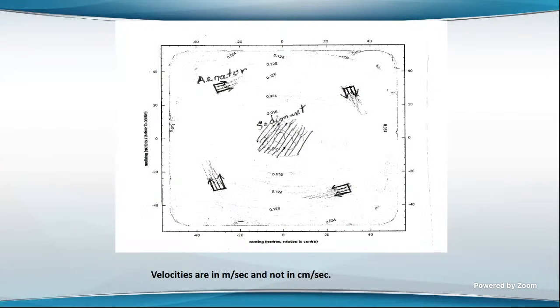And also, when you put aerators in a pond, as I show in this slide, the water velocities are going to be the greatest right out in front of those aerators. If you put several aerators around the sides of the pond and get the water to circulate, they're going to erode the embankments. I'm not sure the numbers are big enough for you to see well, but the highest water velocities are around the edges in front of the aerators, and out at the center the water velocities are much lower, and the sediment accumulates out there, and that sediment becomes anaerobic, and the shrimp won't use that area of the pond.